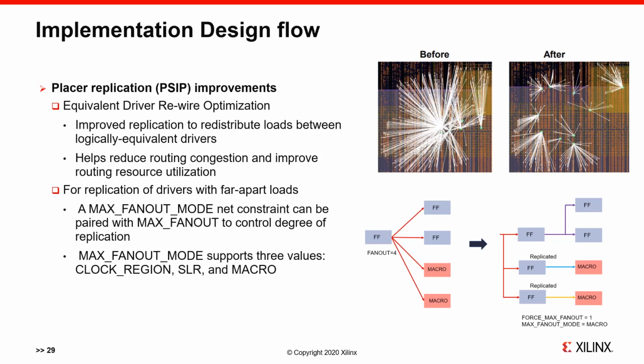For replication of drivers with far apart loads, a max fan-out mode net constraint can be paired with max fan-out to control degree of replication. The max fan-out mode now supports 3 values.